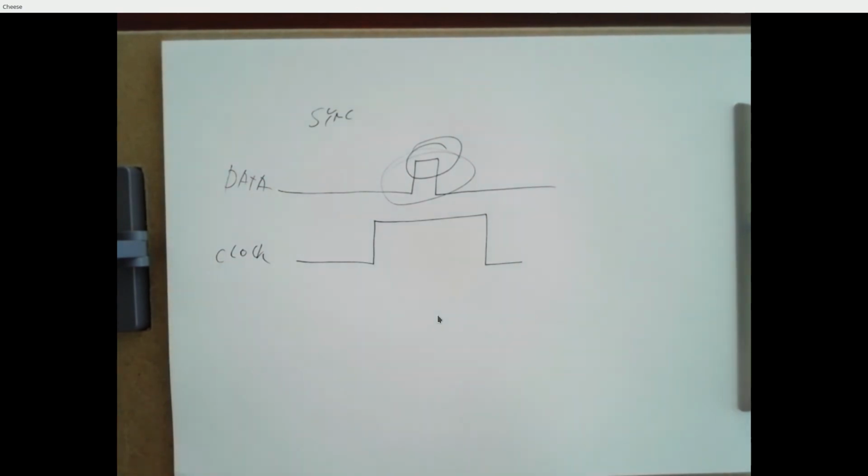And if you do this frequently, in between every character would be extreme, it will take care of these framing errors, okay? So as you crank the speed up, you may find that you want to do the sync pulse more often, but you can start not worrying about it and see how it works. And your goal ultimately is, transmit War and Peace from one Pi to another, and do it across a few wires, see how long you can get these wires to be, and how it affects the noise and the speed and so on. So it's a big experiment.